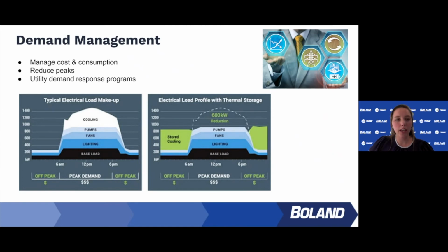So, just one more thing on demand management. I tied this back in because I had thermal storage on the previous slide, but I wanted to dig into it a little more to show you what it means and how it works for a building. We've seen the demand profile: demand increases during the day and turns off at night, and we still have a large demand peak on top.